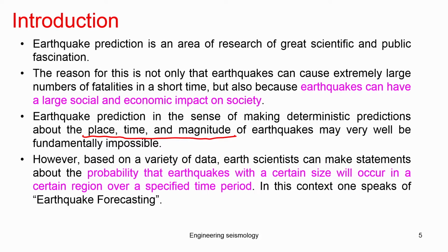I can give you an example. Peninsular India has an average return period of 300 to 500 years for earthquakes of magnitude 6 to 6.5. If we have the complete 500 years of earthquake data, then you can predict the expected earthquake in the next year. But if you have only the last 100 years of data, as India has a poor seismic record, with recording starting only from 1960 onwards, then using about 60 years of data, whatever you predict may not be accurate. Okay, so that is one problem even with accurate forecasting of earthquake hazards.